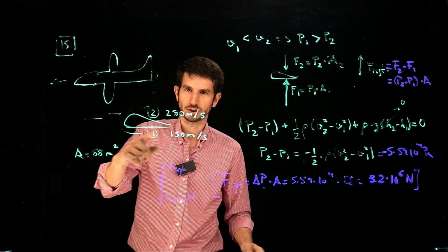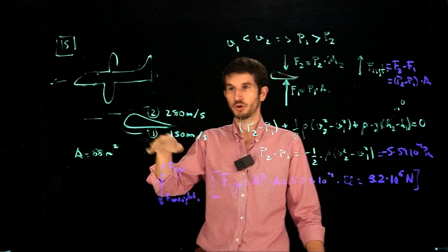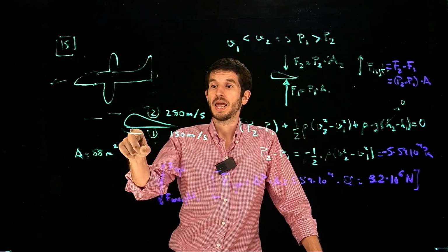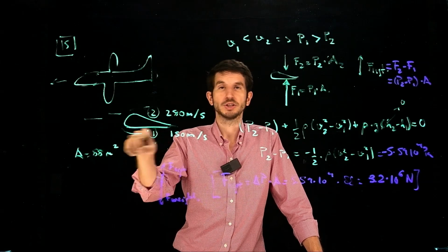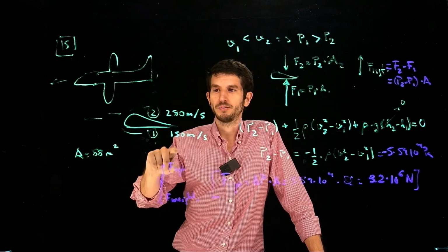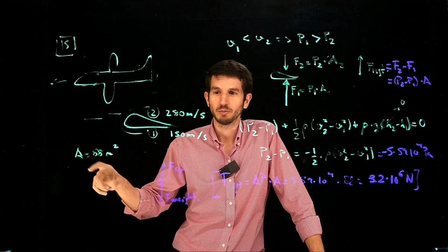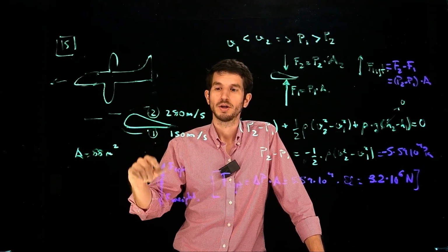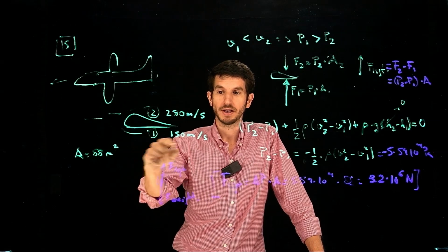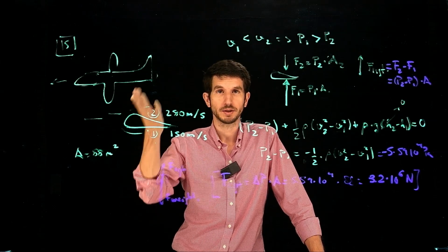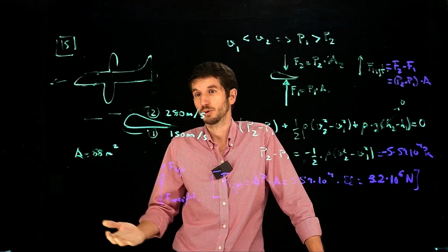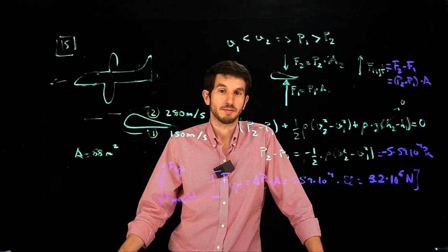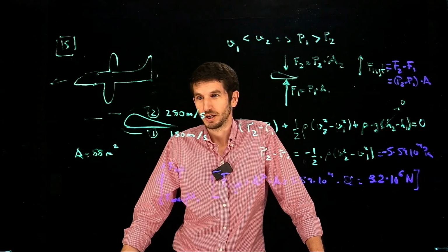So given the velocity that you can go with your airplane in the air, which is given by the engine's performance, and given the particular geometry of your airplane, which is the model, the manufacturers and engineers are going to write a handbook telling you the maximum weight that you can have. If you exceed this load, the lift is not enough to compensate for the weight. You're going to drop, and typically you're not going to be able to take off. That's usually a catastrophe.